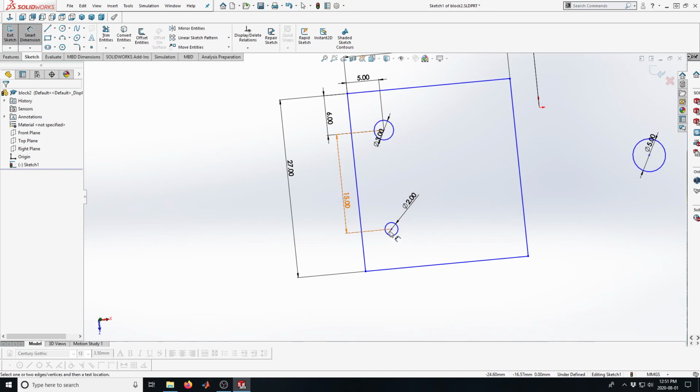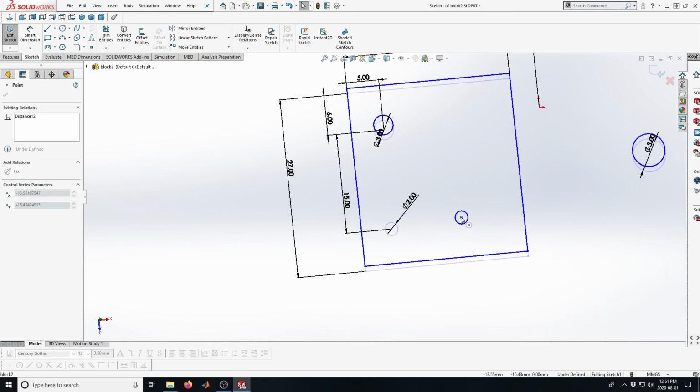Now, if I grab this, actually what you'll find is by the mouse, as you can see with mine, there's a tool which shows that I'm in Dimension tool. And sometimes you want to get out of that. So if you click Escape a couple of times, it goes to just a select tool, and I can move this all over the place.